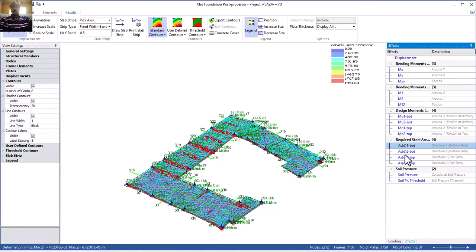At this stage, if you see anything like "section is sufficient", what it's talking about is your slab, which you might need to increase. From 175, which we are using now, you can increase up to 200. If at 200 it is still telling you the section is sufficient, you can go back and increase it up to 250. And if at 250 it's still telling you the section is sufficient, you can ignore it.